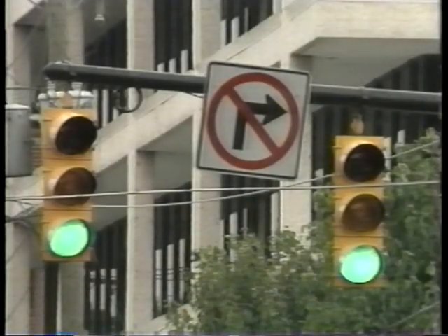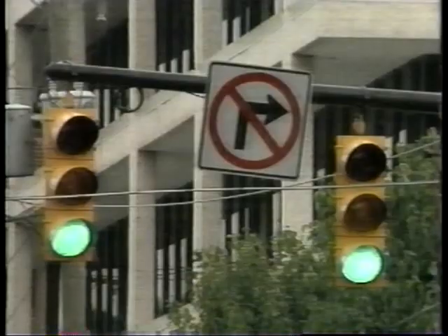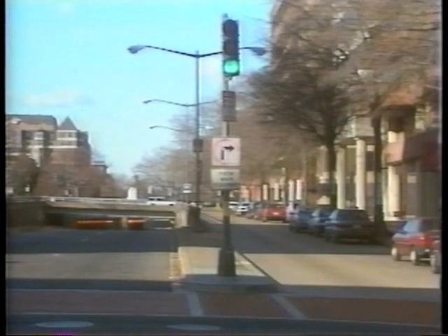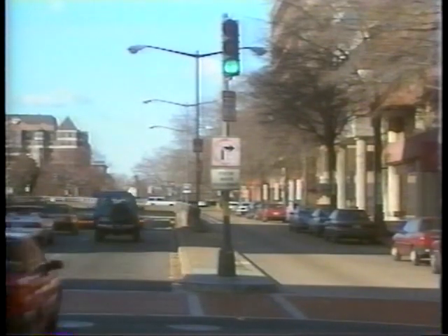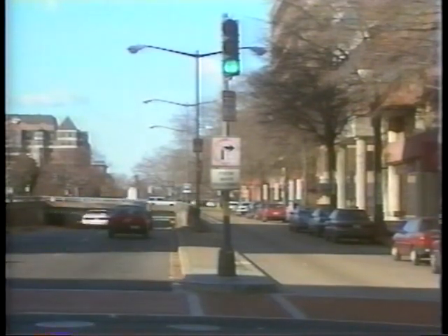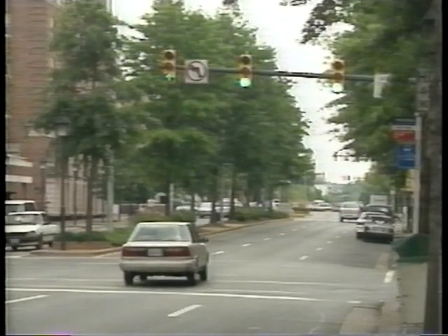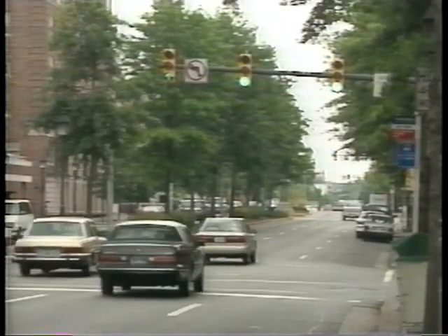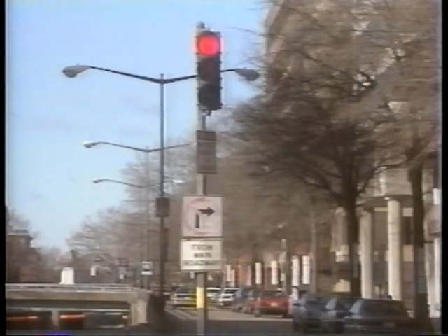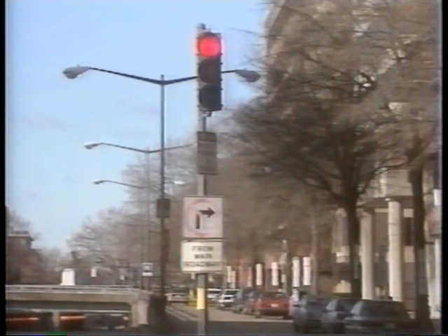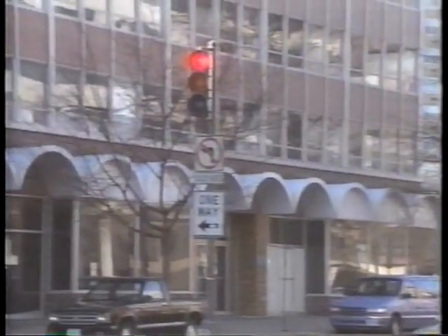No right turn signs should be placed either overhead or on the right-hand corner of the intersection. If there is a signal, the sign can be placed adjacent to the signal face viewed by drivers in the right lane. For no left turns, the opposite placement is required. For no turn signs, use two signs, one on the right-hand corner of the intersection and the other on the left-hand corner.